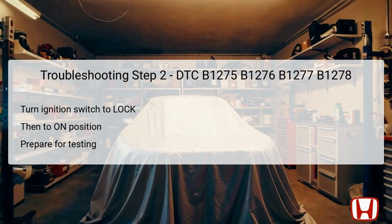The on position activates various circuits without starting the engine, allowing the technician to evaluate headlight switch functions without additional interference. Ensuring the ignition is correctly set is vital before proceeding with additional steps, particularly since incorrect ignition settings can lead to erroneous data during troubleshooting.